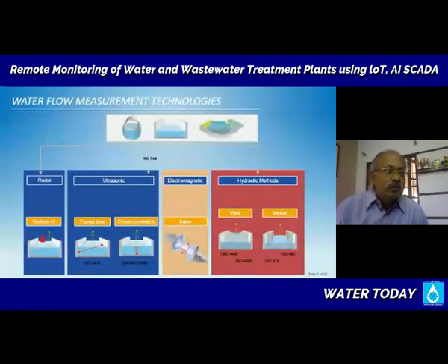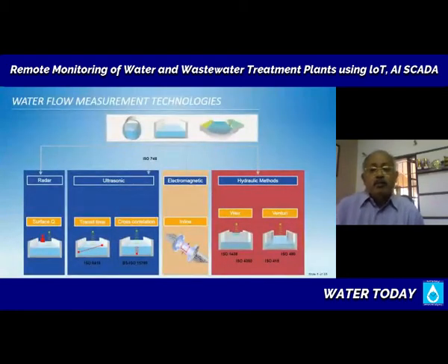Now, one very, very important consideration here is that you need to make sure that the pipe is full. Electromagnetic flow meters do not work under partially filled pipe condition. And also, as you are depending on an electromagnetic induction here, you need to have certain minimum flow velocity, for example, 0.5 meter per second. Generally, you do have some who make meters to a lower velocity, but electromagnetic meters work efficiently when the velocity is 0.5 meter per second.